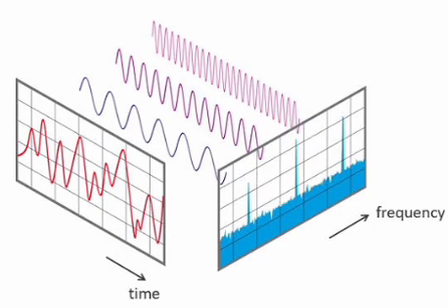The reconstruction of a continuous time signal from the samples can be done using a low-pass filter or a band-pass filter. The spectrum components range from omega L to omega h. The sampling frequency omega s is given by omega s greater than or equal to 2 omega h by k, where k equals the floor of omega h by omega h minus omega L. K must be an integer satisfying 1 less than or equal to k less than or equal to omega h by omega h minus omega L. This is called the floor function.